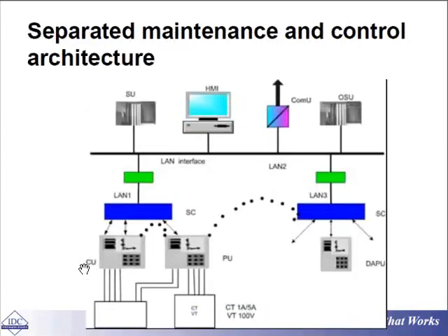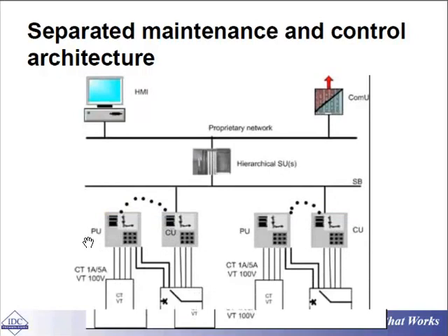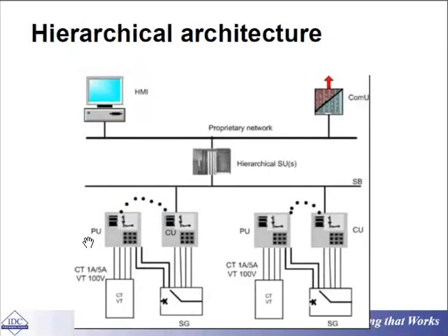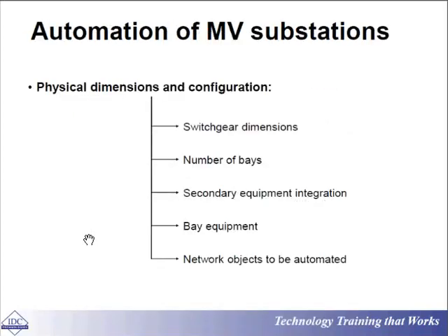Or you can have something like redundant circuits as a means of separated maintenance and control architecture, so that in terms of any fault or outage, you just replace one IED with another one. Or you may decide, rather than putting efforts on the IEDs, you just put your efforts on the buses, the data buses, on the network. You just make it redundant, double reserved or something. So there are many different ways you can improve your system.